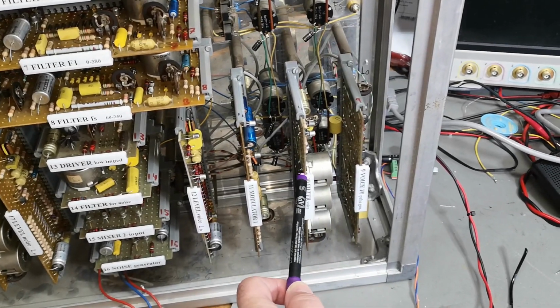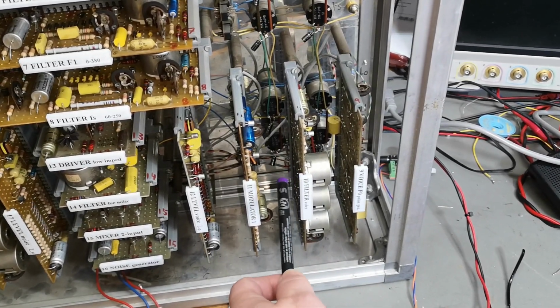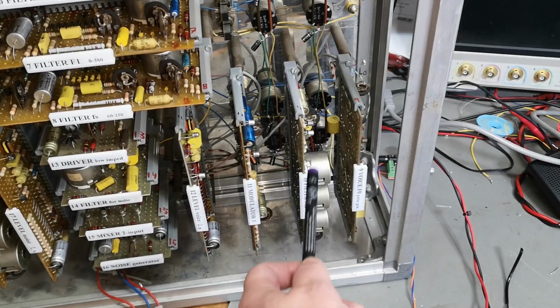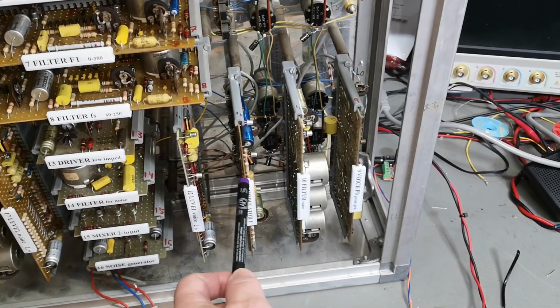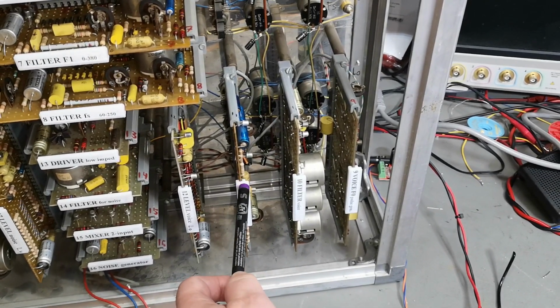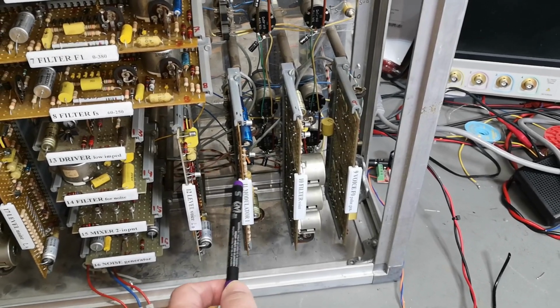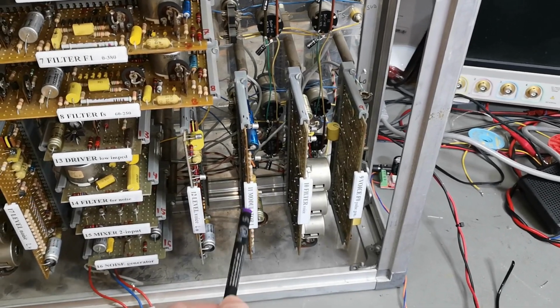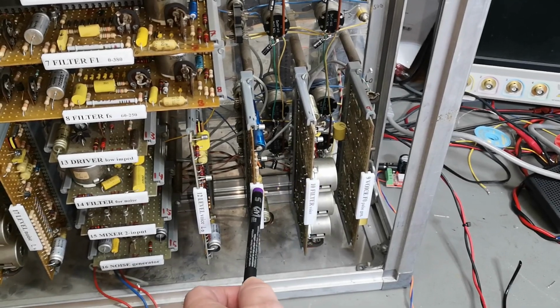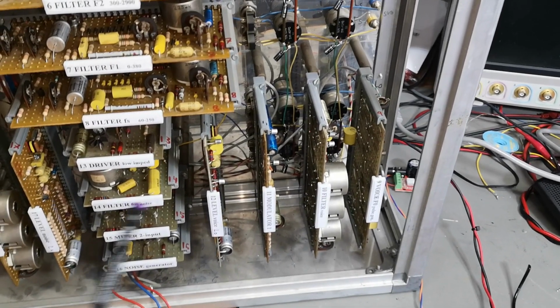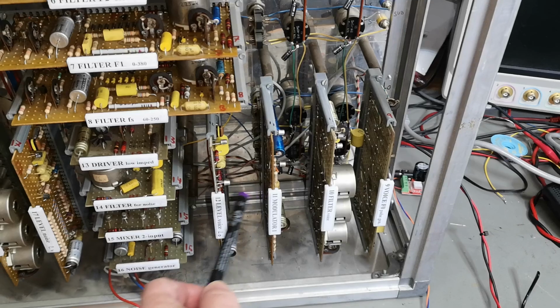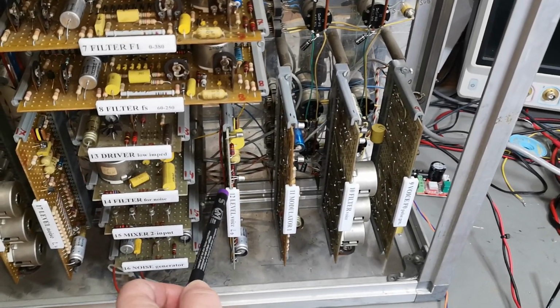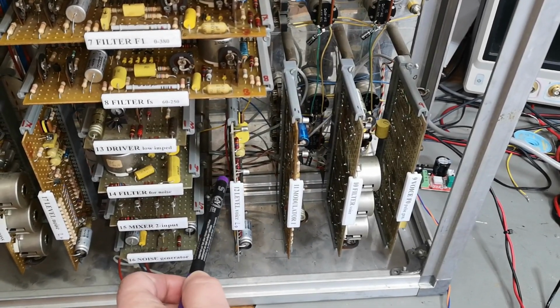The tiny pulse is smoothened or made wider. Then it goes into the modulator. The modulator mixes this pulse with the 8 kHz oscillator signal, and this output goes to a level, DC controlled level.